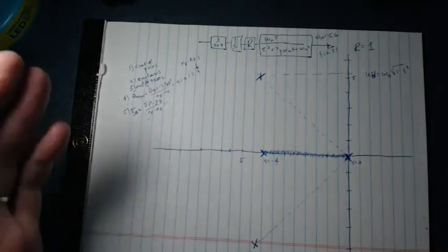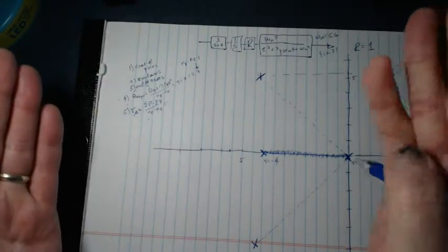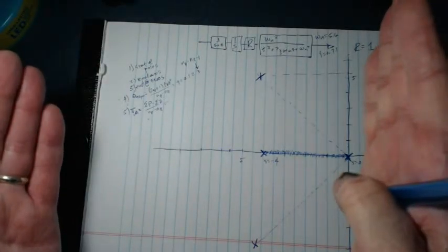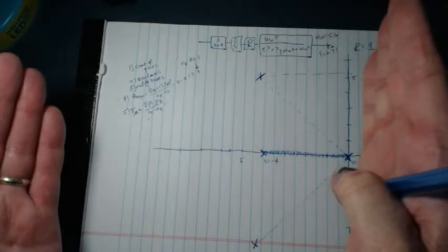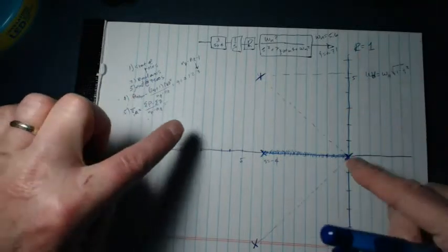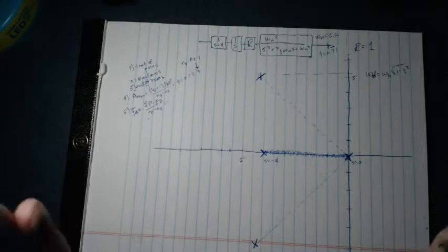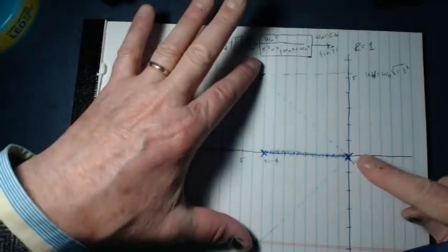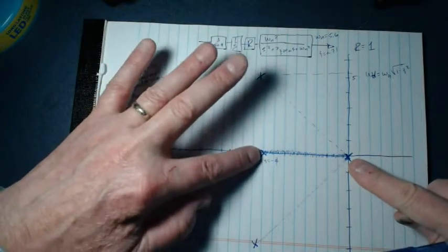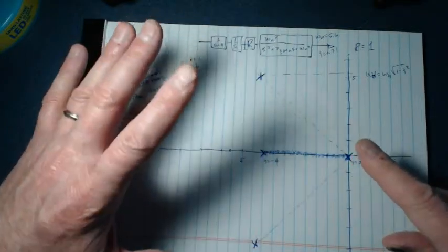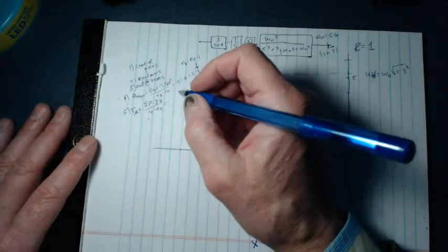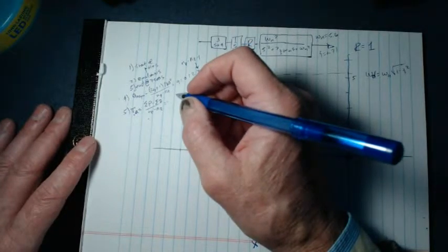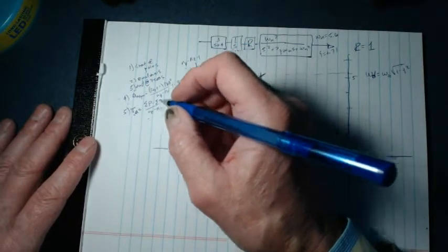One of the things you can think about is that poles, this is like a scale, and the imaginary axis, it's like these things push up. X's push up, and if you have any zeros, they push down, and it's like the center of effort for all of these things. But if we're going to do this sum of the poles minus the sum of the zeros, this is going to be